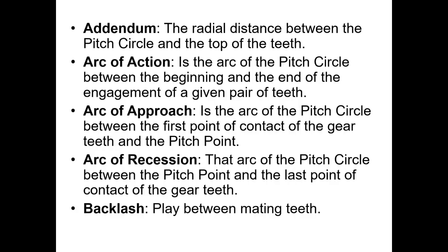First, what is addendum? The radial distance between the pitch circle and the top of the teeth is the addendum. Next, arc of action is the arc of the pitch circle between the beginning and the end of the engagement of a given pair of teeth.